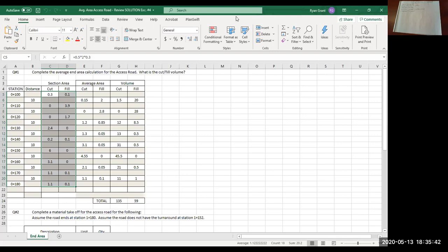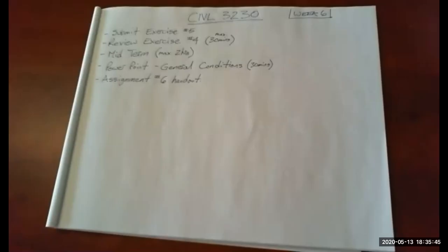So let me share a different screen to show the cross sections. So this is an on-screen takeoff software. This specific one is PlanSwift. That one's kind of hard to see. Here's a good one. So 0 plus 110. So the blue area is the area that you should have calculated for the fill. This white rectangular strip is the road structure for the path.